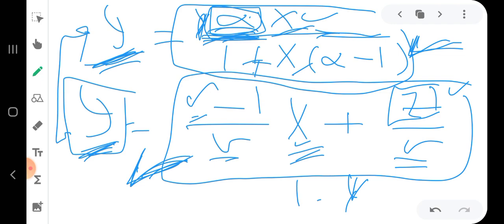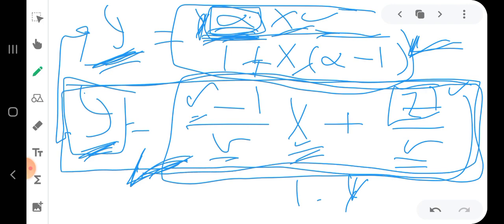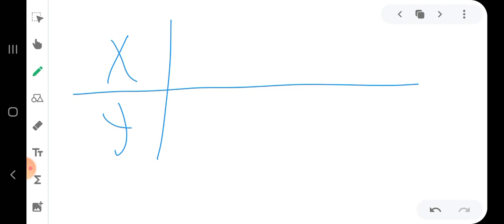And what do we mean by the graphical solution? The material balance line will be fixed, but we will not have the equilibrium equation because it depends on the relative volatility. Instead, we will have equilibrium data x and y with specific values obtained experimentally.